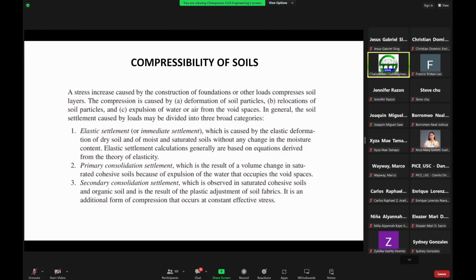That's actually under the principles of soil dynamics, wherein we try to consider also liquefaction settlement, where liquefaction is a behavior of some types of soils where it tries to liquefy. It acts like a liquid during an earthquake, depending on the magnitude of the earthquake, and also depending on the groundwater levels.